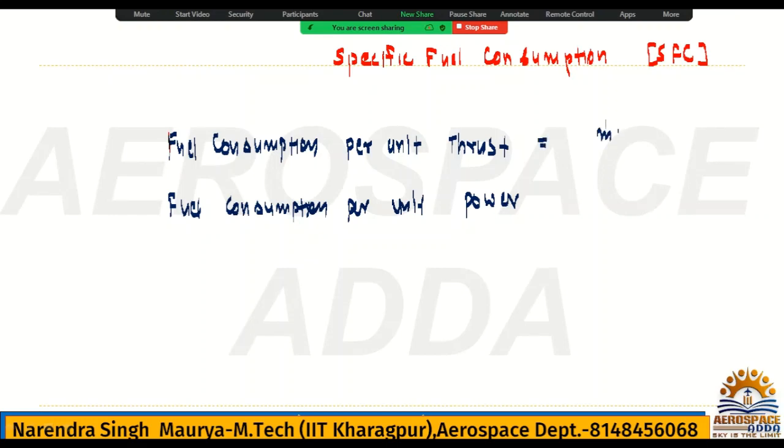Fuel consumption per unit thrust, or fuel consumption per unit power. If it is fuel consumption per unit thrust, then it is called thrust specific fuel consumption, I can say. And if it is power, then we can say power specific fuel consumption.